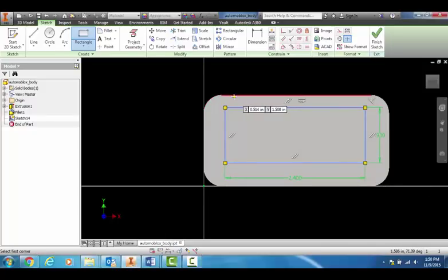But if you also remember, we have to center this rectangle now, and it had a distance of 0.39 from the sides and 0.3 from the top. So we've got to center this. Let's hit the dimension button here. When you use the dimension, click on the line, move your mouse down, click on this line, then click again.